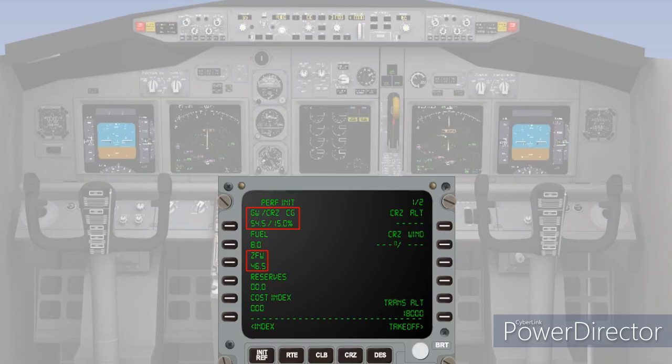Performance calculations are produced when the flight management system is initialized by entering values of weight, route information, target altitude, and cost index. A cost index is a figure provided by the company which is entered by the flight crew to determine the optimum performance with respect to fuel burn and trip time. The default performance mode is economy, using the minimum fuel for the minimum flight time.